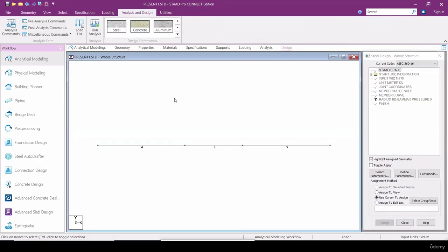You are seeing just beams here, right? You do not have information about where the node is located. Can you observe here? There is no node. You cannot observe with the naked eye. There are nodes here, but you cannot see them. If you want to see a node, that is Shift K. Shift K is the command to see the nodes. So that is all about it.